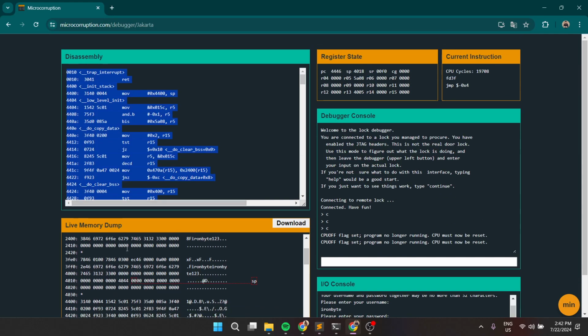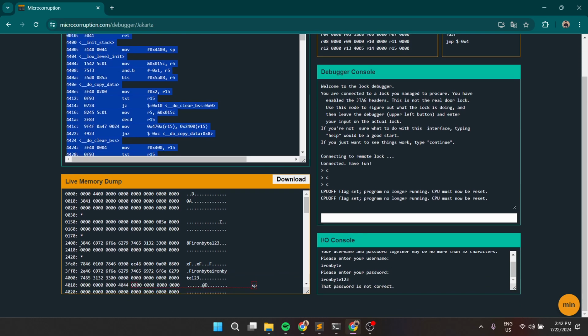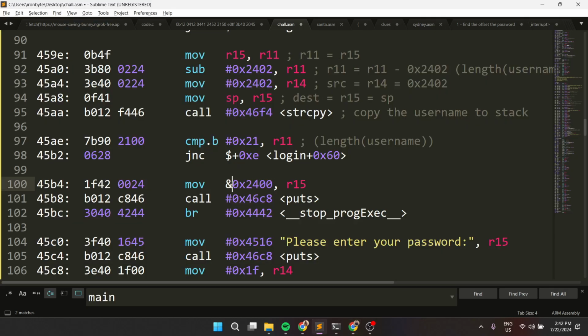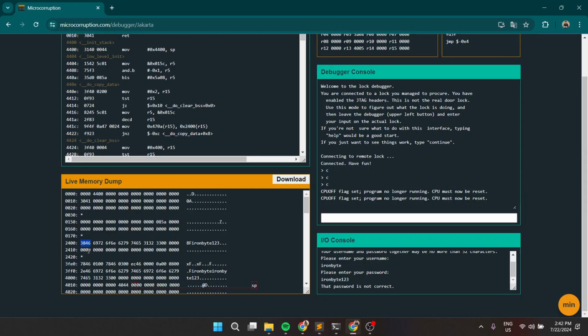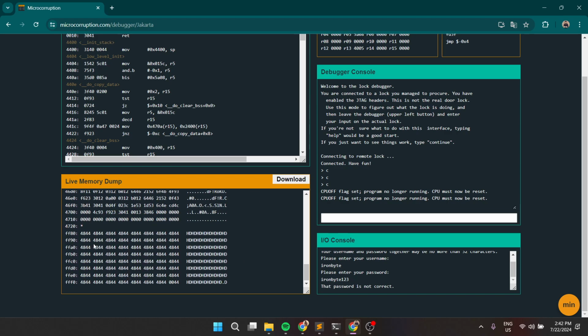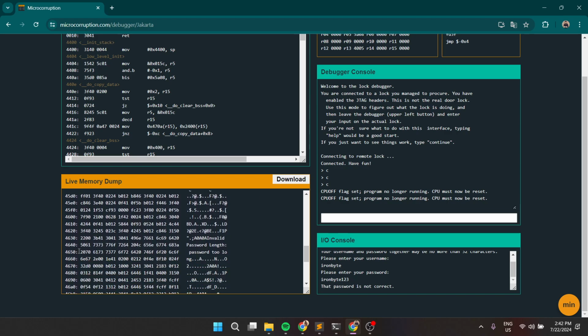So for example, we have to check what 24 is having. So this address. When we add the AND, he's basically going to be interpreting that as an address and flipping the order of the bytes since it is in little endian. So it's going to be 4638. So if you check 4638,